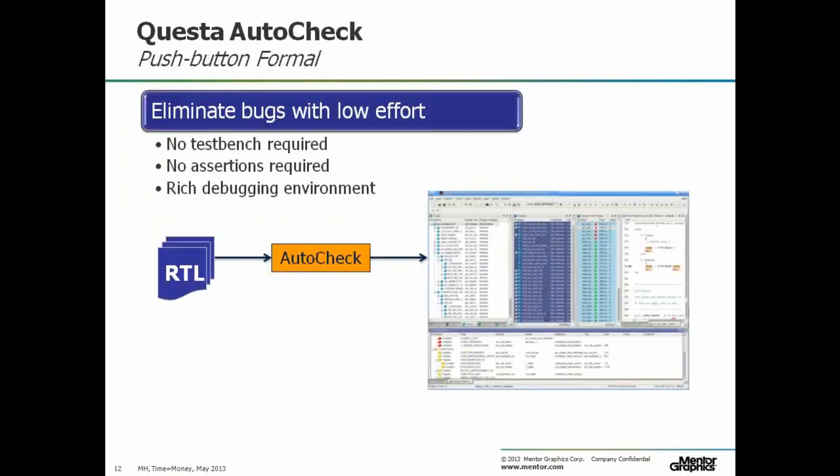So we can do things like what is often referred to as superlinting. So some structure-based checking of your RTL. The beauty of this is it can be done very early in the flow. So you can throw RTL at a problem. Tools have canned rule sets, if you like, defined checks that they're going to check against your RTL for. And this will also include your own constraints from your own file. Absolutely, yeah. So you can throw RTL at it.